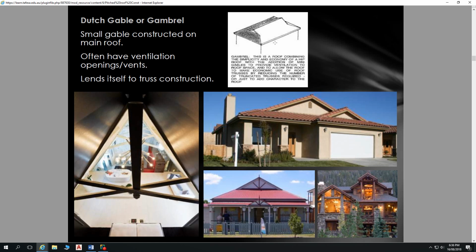So you could, with the eaves, that's the underside of the roof as it extends past the walls. We can cover that section completely with fibre cement sheet and not have any air in there, or we can actually cover that eave with timber slats and then mesh over top of that to stop birds getting in. But then that allows hot air to be sucked in through the eaves, or cooler air to be sucked in through the eaves, and all the hot air exhausted out the top of the roof with the Dutch gable.